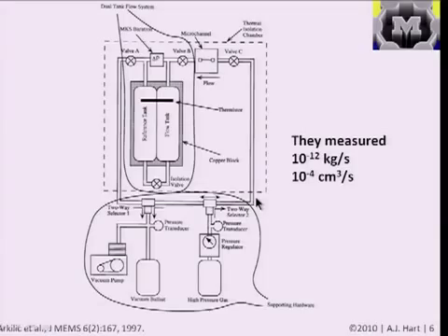And as a calibration, if you're building a reactor to, say, deposit a film or grow some nanotubes, and you buy commercially available mass flow controllers, pretty much the lowest range you can get is a few cubic centimeters per minute, or maybe an order of magnitude less than that. And it's very difficult to measure such small flows.